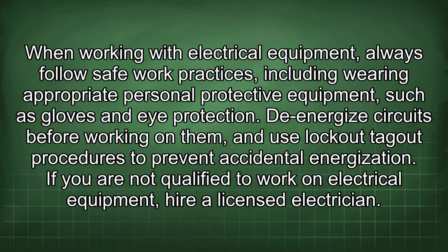When working with electrical equipment, always follow safe work practices, including wearing appropriate personal protective equipment, such as gloves and eye protection. De-energize circuits before working on them, and use lockout-tagout procedures to prevent accidental energization. If you are not qualified to work on electrical equipment, hire a licensed electrician.